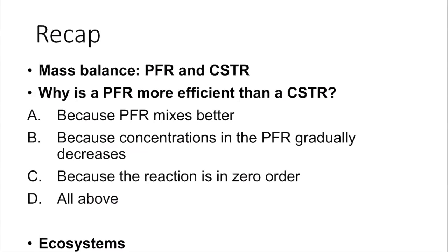Okay, 5 more seconds. All right, we'll stop here. It's nice that almost all of you got the correct answer. Okay, so it's because in the PFR the concentration gradually decreases, right? And that's why you can have a higher reaction rate for the pollutants when it first enters this reactor here.